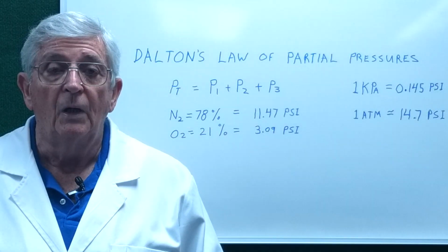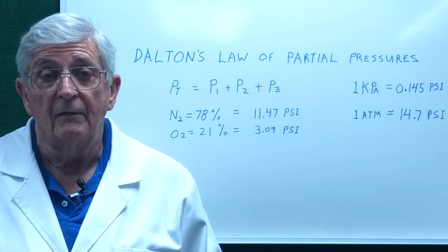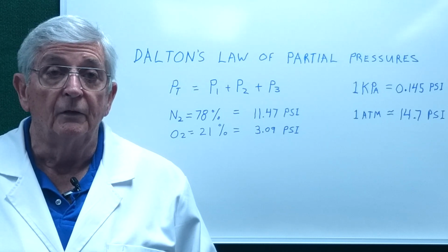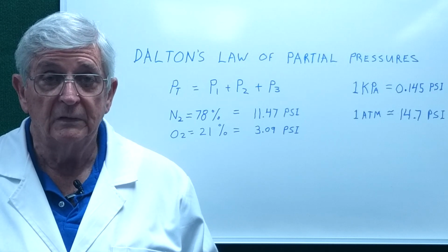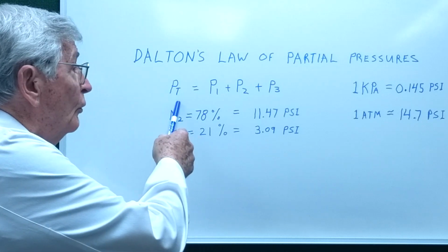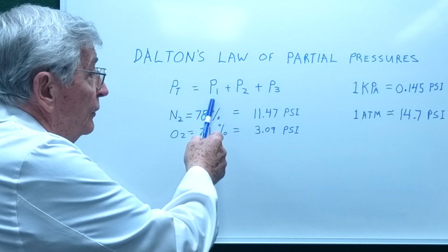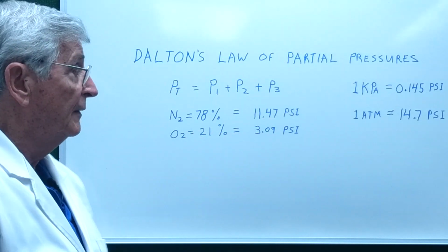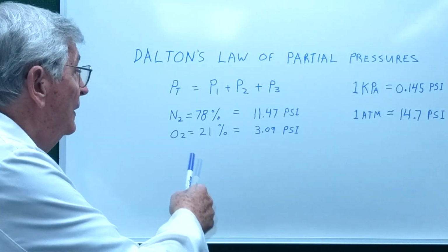To fully understand relative humidity, we have to have an understanding of partial pressures. There's a law called Dalton's law of partial pressures. Basically what it says is the total pressure of a mixture of gases is equal to the sum of the partial pressures of each individual gas. Now, in the case of the atmosphere around us, we have